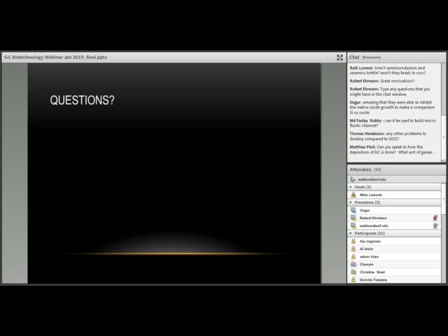In the case of silicon carbide, the good news is that the native oxide is also silicon dioxide, but it grows very slowly. So we went through the same trouble. The last chemical cleaning step before immersing it in cell culture was to use buffered HF. And again, directly, we literally rinse it in DI, immerse it in ethanol, and then go off to the biolab to do our cell culture.